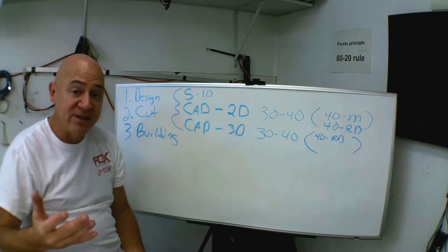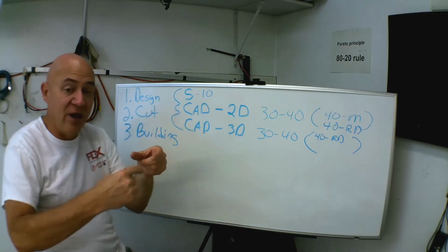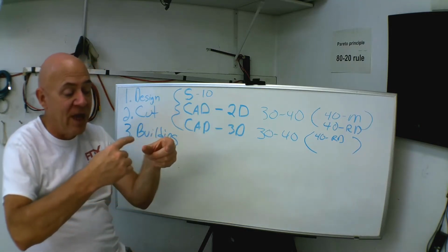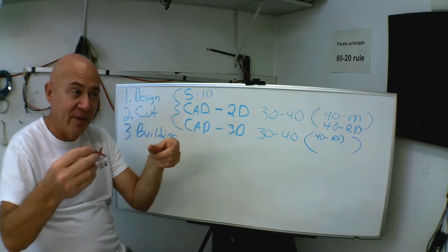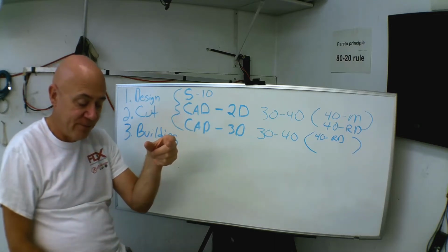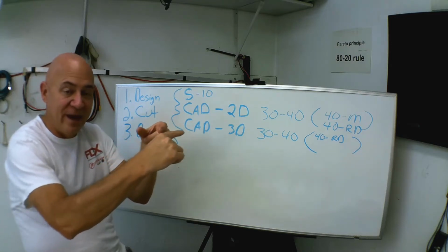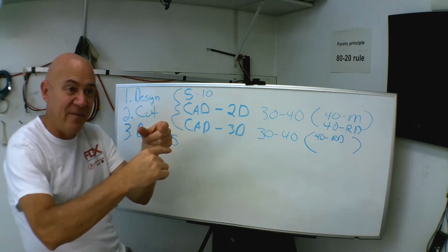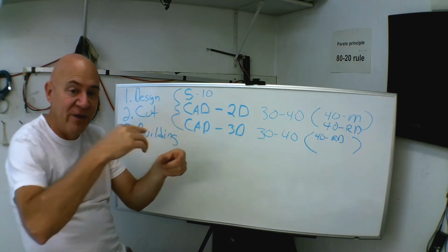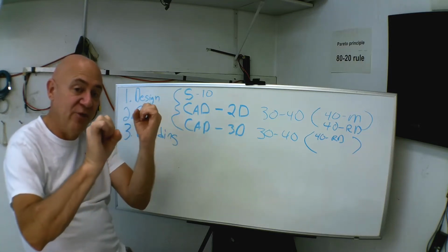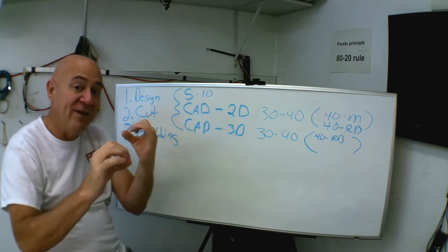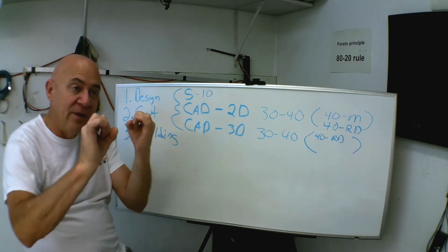Now what I did on this little mistake I made is go underneath each rib in the pink foam, and I took a little hacksaw blade and sawed out about an 1/8 inch groove into the first 3 ribs, so I could move that wing tube down.